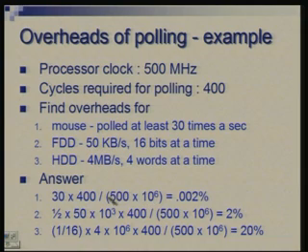So, as a fraction or as a percentage, what is the fraction of the cycles which actually are lost in this activity and not in executing other computational instructions? So, we divide the number of cycles per second consumed by the cycles per second available, we get a ratio, convert that to percentage, you get 0.002%. So, it is a very small fraction of the time which is spent, and we will certainly not mind doing polling of the mouse in this particular manner. Okay. Very little overhead.